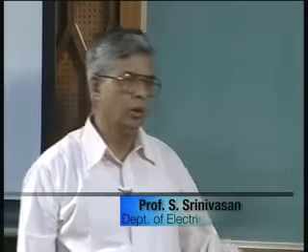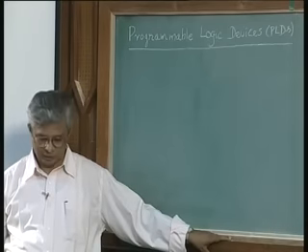Today we will talk about programmable logic devices. Programmable logic devices are building blocks which are used to realize digital systems. They can be used to design combinational logic, and also they can be used to design sequential logic. Today we will see some of the basic PLD, programmable logic device types, and take simple combinational logic examples. In a later lecture we will talk about sequential circuit implementation using programmable logic devices.